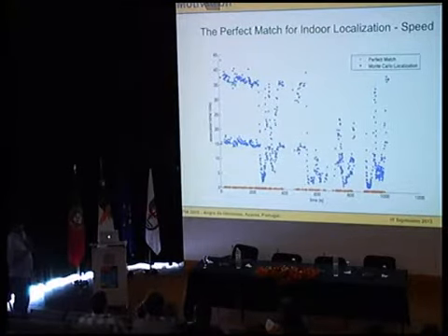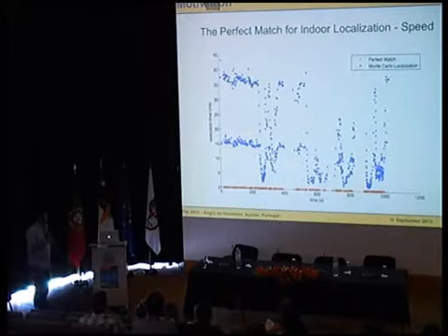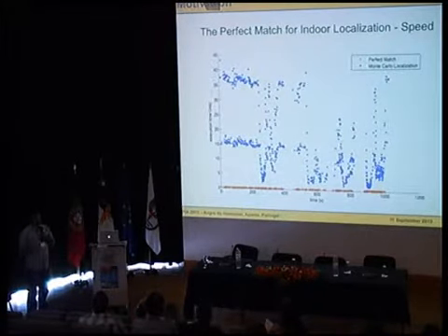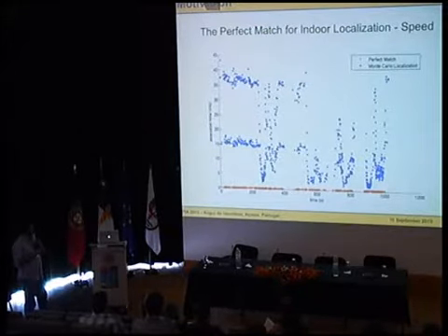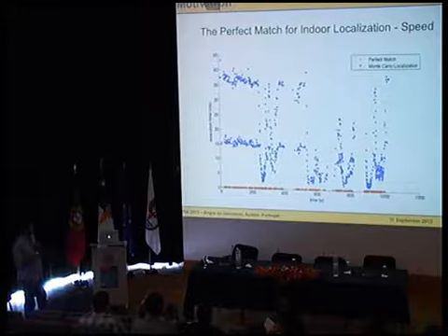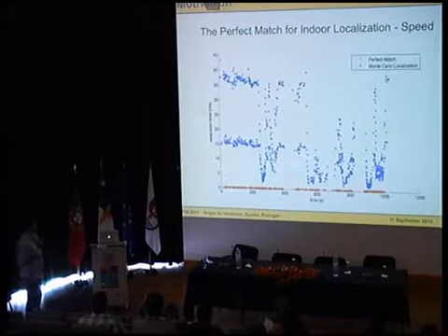First, its speed. I compare it with the Monte Carlo localization, which is a particle filter localization algorithm. The perfect match always goes through 0 or near 0, while the Monte Carlo localization has somewhat higher execution times.